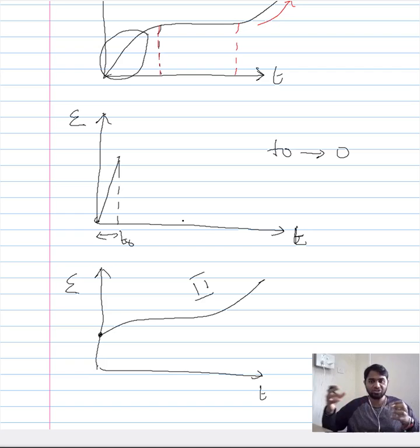That means there is an instantaneous elongation, and when you want to plot an instantaneous process in a similar curve along with the other process that occurs at a very low rate, it becomes difficult, and the instantaneous region gets sidelined and becomes more insignificant. That is the reason, for practical purposes, this instantaneous change in the dimension of the material at the early stages of creep testing will not be shown. And that's why, for practical application, the creep curve of form 2 is adopted.